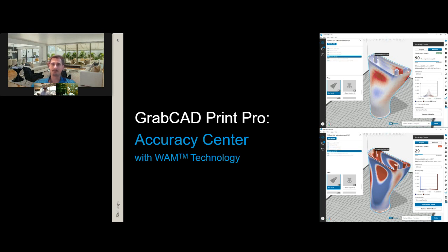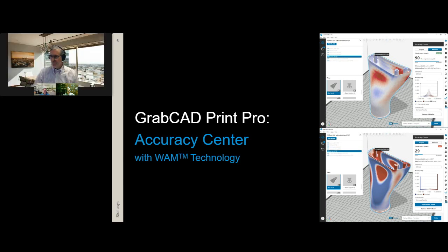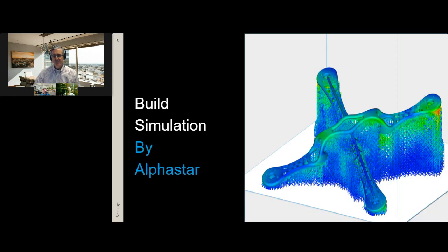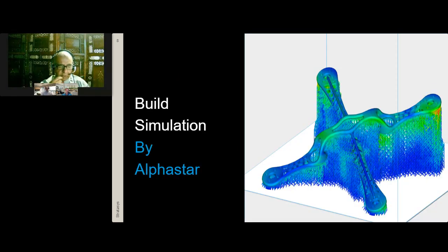Gotcha. Okay, thanks. Rashid, we've got one for you, which is how long does a simulation take? Well, it generally depends on the size of the build and any requirements regarding resolution of the simulation itself. But generally for the air gap analysis, probably 2 to 5 minutes. And for thermal analysis, depending on fidelity of the model, it can take anywhere from 30 minutes to about an hour. But again, you get a fresh set of eyes, a chance to really see what's going on, and it sure beats 3 to 4 hours of a build and lost material time and personnel time.